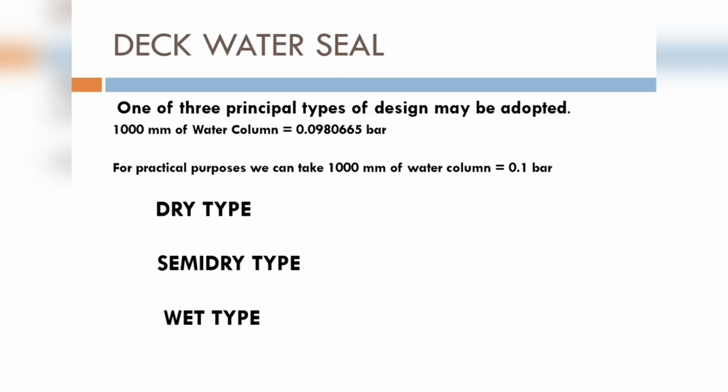Those who have worked on a tanker know it's quite a lot. We need to release some gases. This pressure is going up, but practically speaking, it is equal to 0.1 bar, and a cargo tank can withstand only 0.5 bar. That's why you have so many pressure release systems and safety devices installed on the system to keep the cargo tanks safe and protect them from damage.